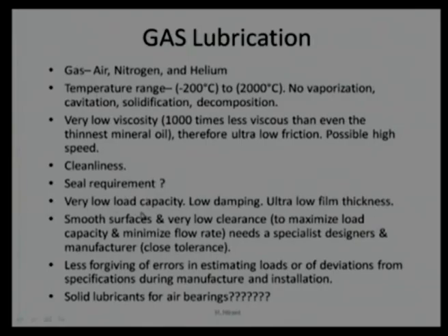We say this kind of lubrication is effective when the load requirement is not very high, the applied load is very low. We do not require any damping, or there is no vibration related problem, and even ultra thin film thickness is sufficient to separate two surfaces.